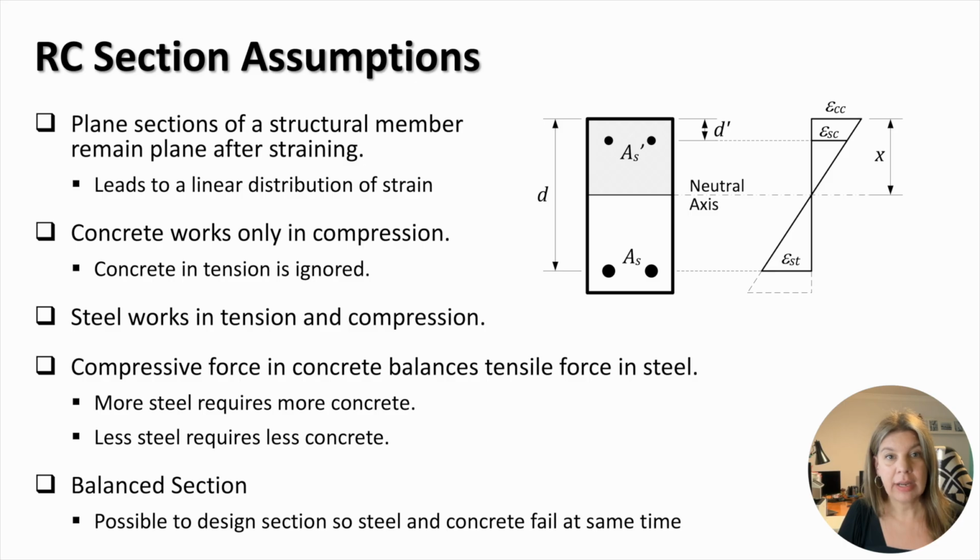In the picture on the right, you can see a typical reinforced concrete section, where the top and bottom reinforcing bars are shown in full black circles. The linear strain distribution through the section depth is shown on the right. Note that the two intersecting lines comprising the strain distribution basically represent the plane cross-sections before and after deformation.